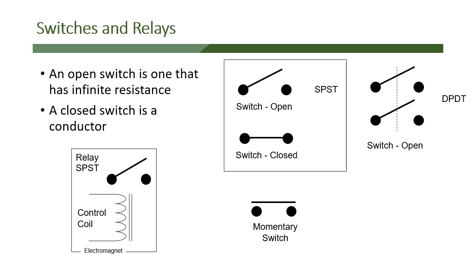We also can have a switch that can be powered by a coil. So here we have a coil. Remember, when you run current through a coil, it produces a magnetic field, and if the throw part of the switch is a compound like iron or steel that is attracted to a magnetic field, then it will pull down and go to the circuit that we want to switch, and it shorts out and causes a current to flow. So we apply control voltage to the coil. It creates a magnetic field, which is an electromagnet. Because the throw on the switch is an iron compound, it will then push down and make contact with the circuit and allow current to flow. When we turn the current off on the control coil, it will demagnetize, and the switch will then pop back up and open again.